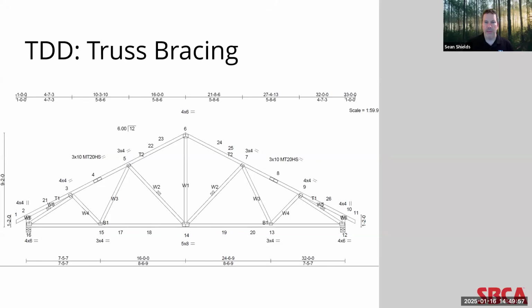So, as I mentioned, trusses perform well within their lateral plane, but sometimes the forces designed to go through a web or cord in compression, so in this instance, let's say these two webs, these webs, when in compression, could cause the truss members to buckle out of plane.